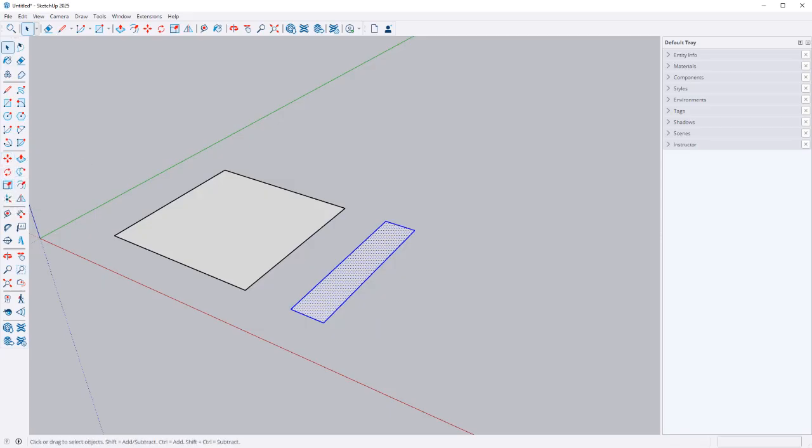Let's talk about rotate really quick. The rotate tool is going to take a face and rotate it in a direction. You click on wherever you want your rotation point to be, and then you click on a starting axis and an ending axis. So I can rotate this around any way I want, or I can enter a number like 90 degrees and it'll rotate it 90 degrees.